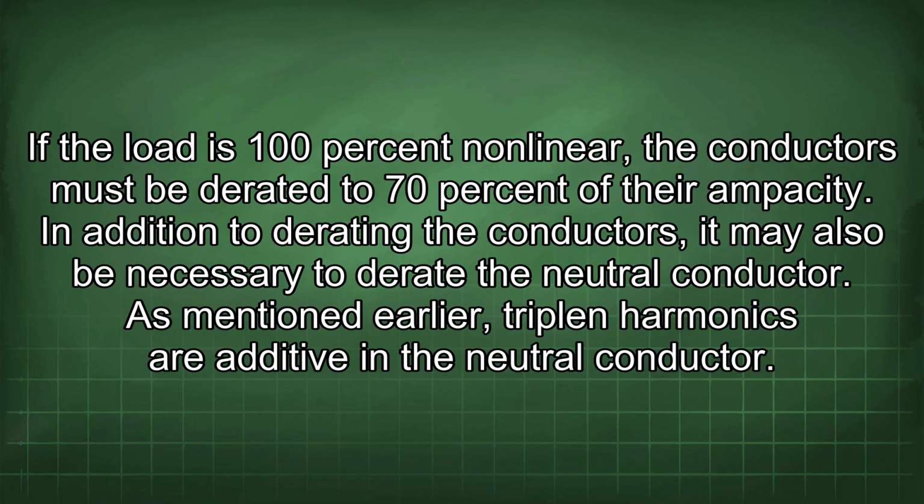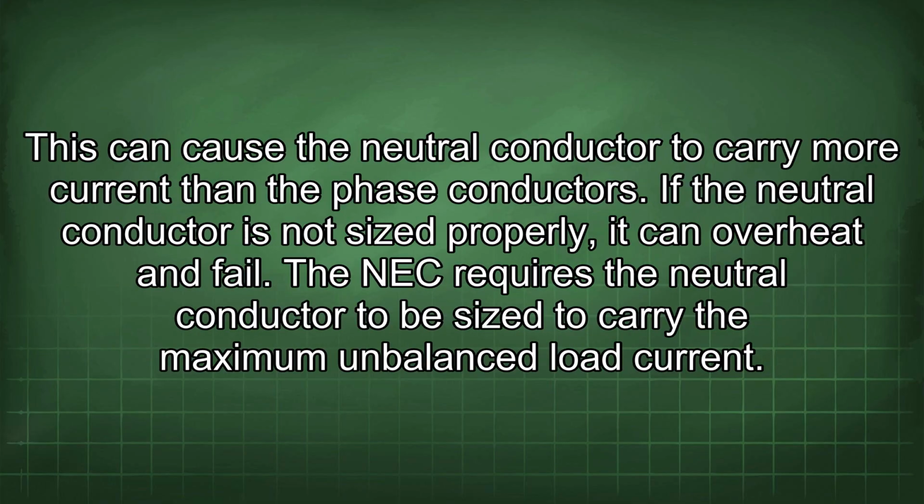In addition to derating the conductors, it may also be necessary to derate the neutral conductor. As mentioned earlier, tripling harmonics are additive in the neutral conductor. This can cause the neutral conductor to carry more current than the phase conductors. If the neutral conductor is not sized properly, it can overheat and fail.